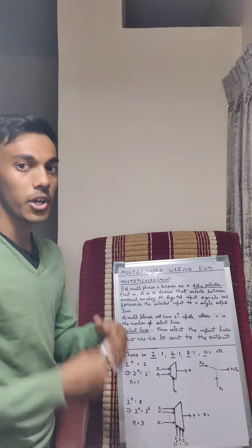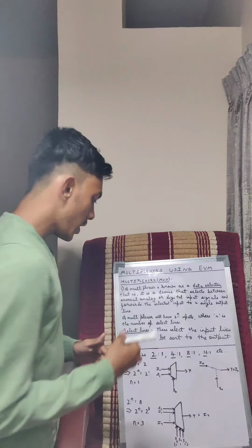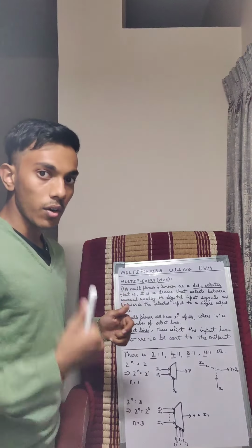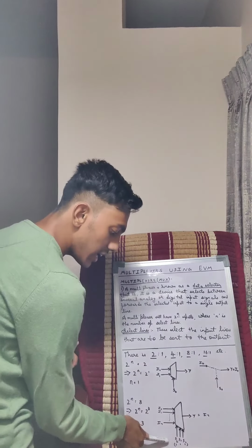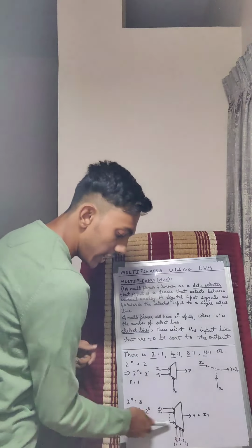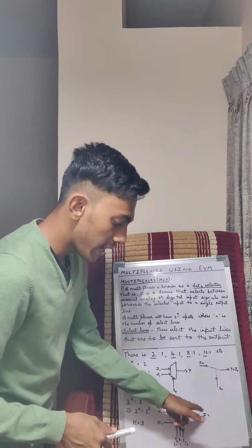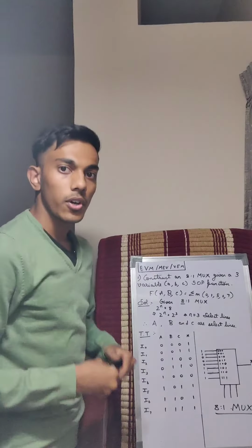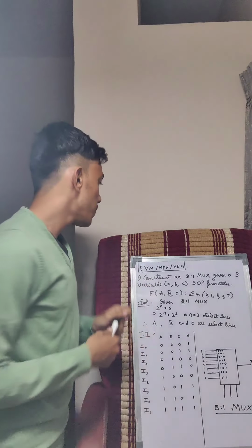And as we all know, there's going to be only one single output. Now, for instance, if I want the output as I7, the inputs that the select lines will consider will be 1, 1, 1. So they will map to I7 and that will give out as the output. Y is equal to I7. Let's move on to our next topic. I would like to mention another thing.